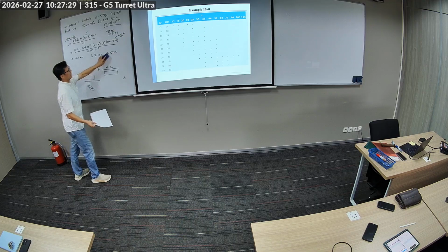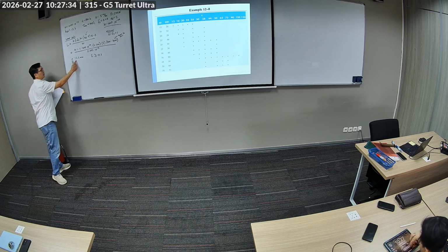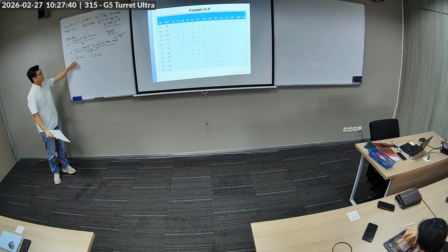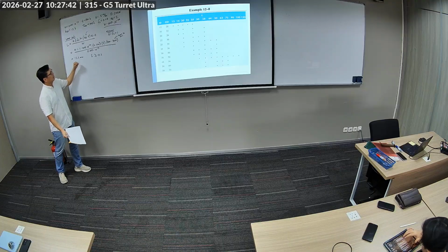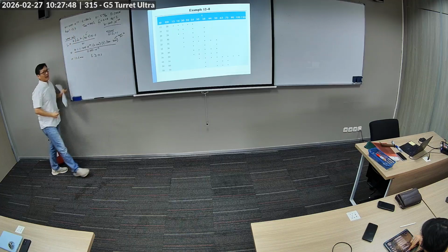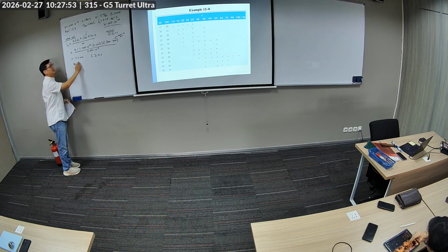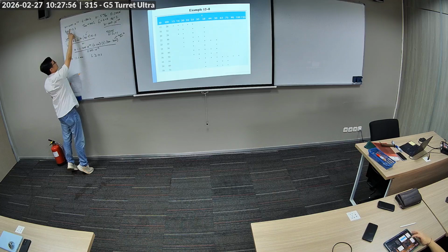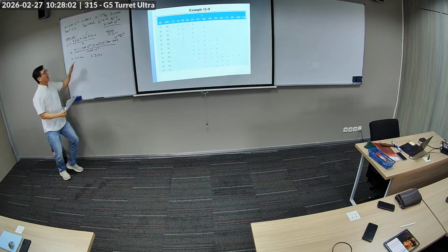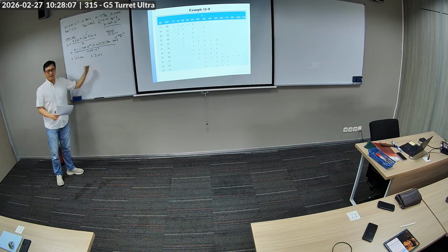So I want L to be bigger than this threshold. Because this 12.2 is the critical point, right? Basically, 12.2, with these assumptions, will reach the wear limit at 800 hours. That's what that number means. If I select a bushing with 12.2 millimeters, assuming all that, it'll reach this wear limit in 800 hours. So if I want a minimum of 800 hours lifetime, I have to have an L bigger than 12.